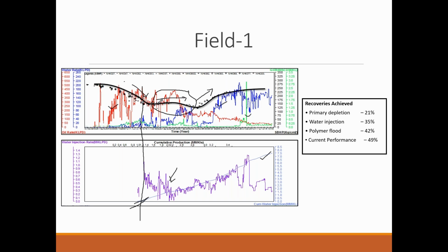And after that, you can see that the pressure has stabilized. And as we have increased the water injection rates, the reservoir pressure is also going in an upward direction. So this was one part of it, where we can see how reservoir pressure has responded in a particular reservoir, how the fill up part has been identified, and what the response time is. All these things can be inferred from this particular field plot.